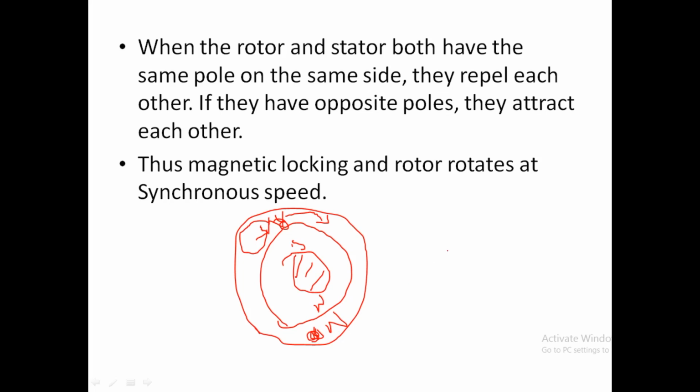So for an entire cycle, these will cancel each other and the average torque will become 0, and the motor will not be self-started. It will not be self-started. So that is the main issue with the synchronous motor. Synchronous motor will not be self-start. It is not a self-starting motor.